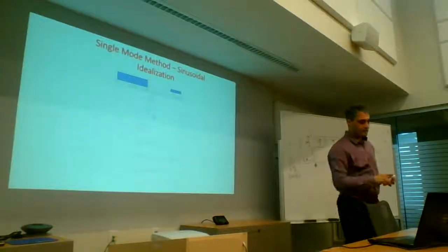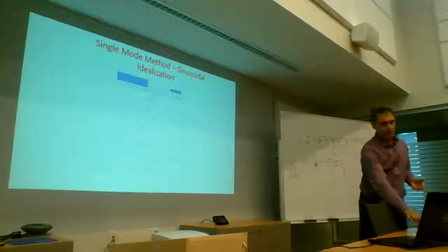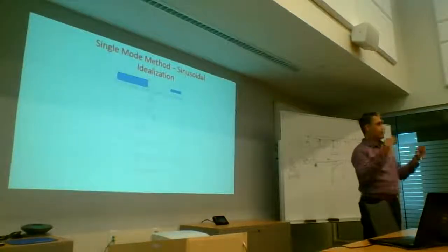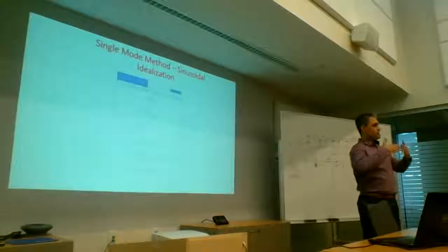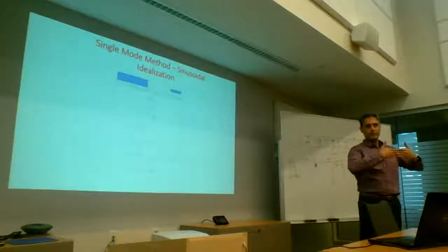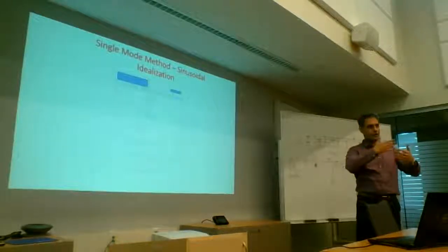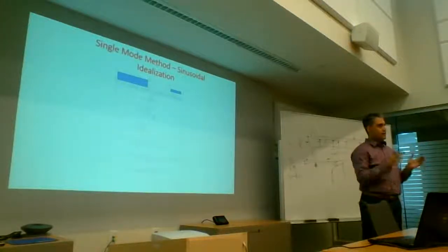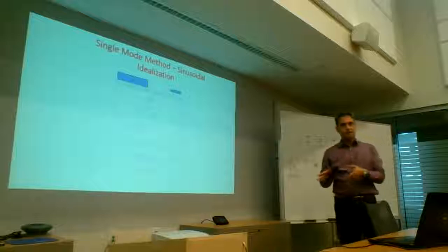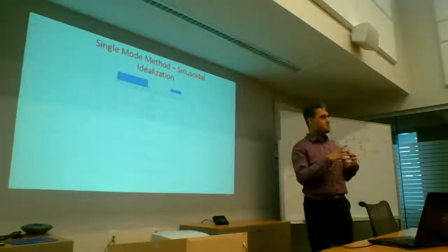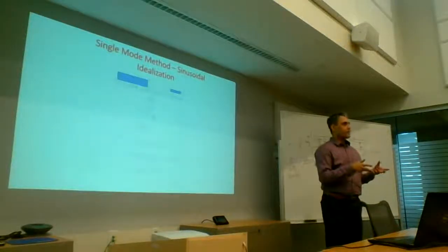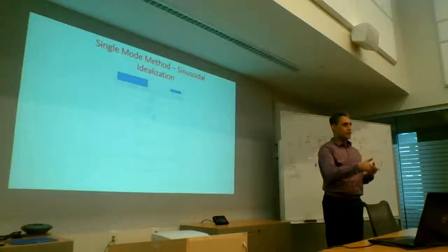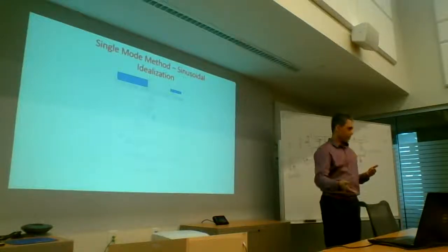Now, here's my personal thought about it. You still need to have a bit of a model set up, right? To apply that initial 1 kilonewton per meter or 10 kilonewton per meter load to get your basic deflections, to get your stiffness. By the time you've done that, you've basically made all the effort. Let the program do the work after that and come up with the mode shape.